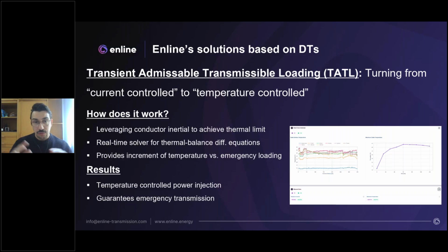Of course, controlling this injection under safety levels. And this would be the dynamic line rating with this assisted layer to control the transients. And it's another component we believe fundamental for the controlling of grids, with more emphasis in the stability of the grid once you have to achieve some overload situations.